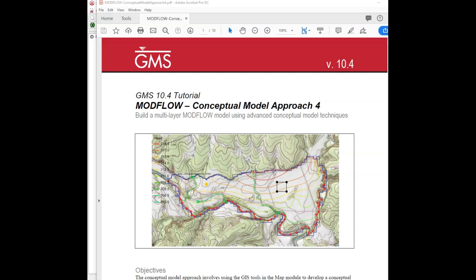And we're also going to play with our hydraulic conductivity values. And then finally, we are going to make some changes to how we simulate this well on the right, specifically how we allocate the flow rate between multiple layers, and we're going to use one of the advanced well packages to do that. So, as was the case with the other